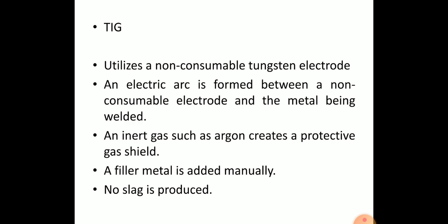TIG welding is not often used for welding plates thicker than 6 mm. In MIG, it is best suited for jobs thicker than 6 mm. In TIG, penetration is not so deep as in MIG. In MIG, deeper penetration can be obtained as compared to TIG.